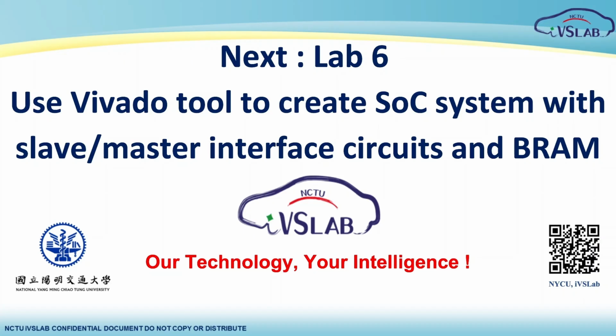In Lab 6, we will implement a VRAM controller, enabling the CPU to directly map and access memory blocks inside the FPGA fabric. This milestone means the CPU can burst write entire batches of data into VRAM or read back massive blocks of processed results simultaneously.